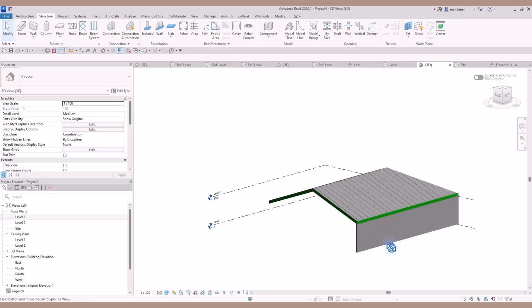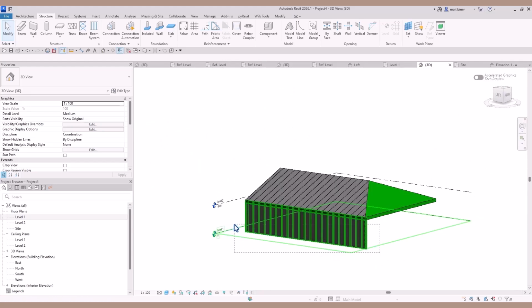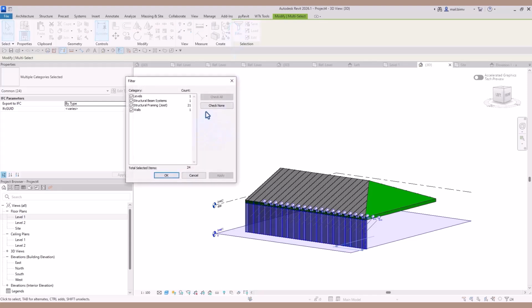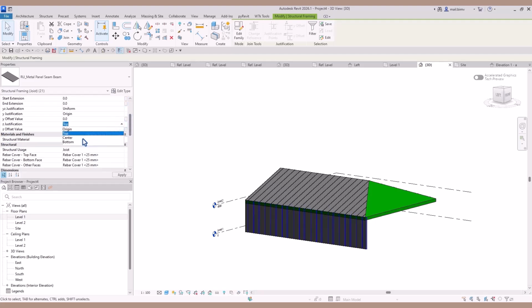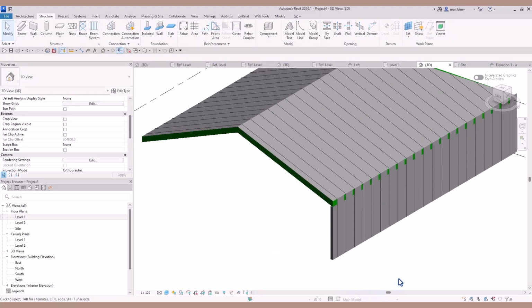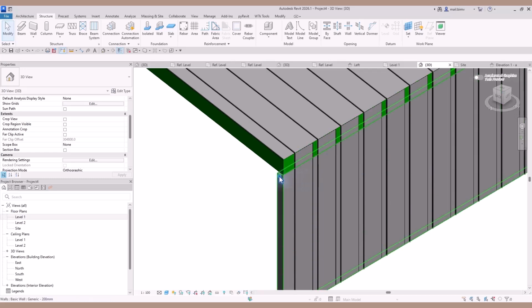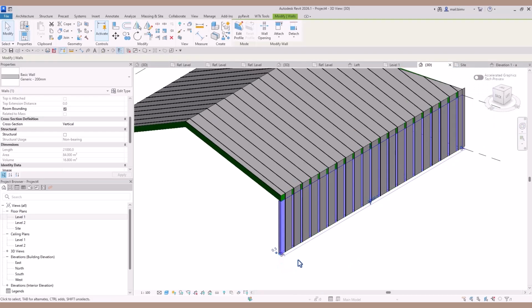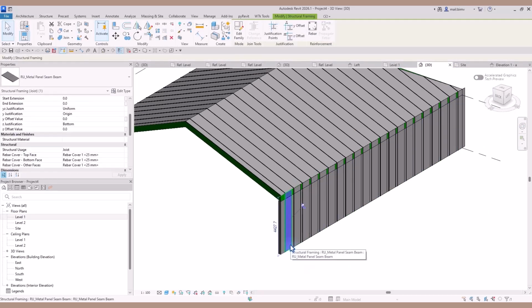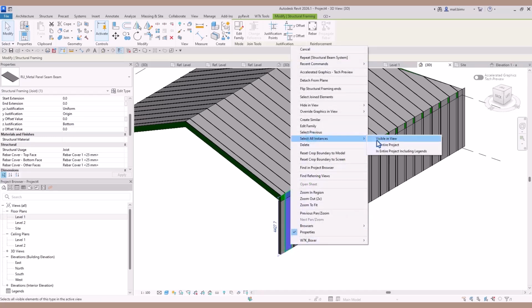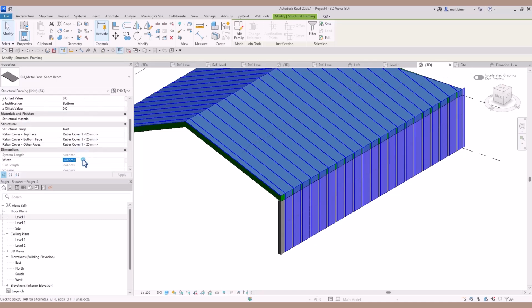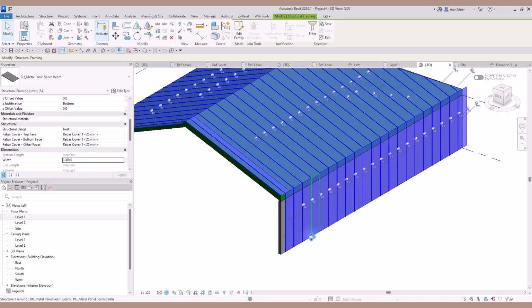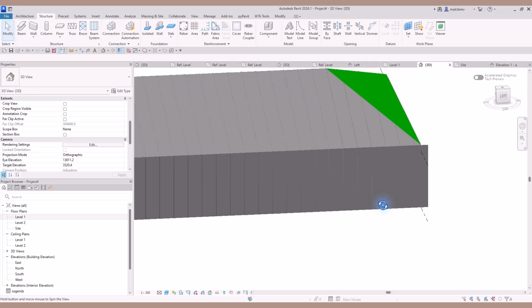I'm trying to select the beams in order to modify the justification, so I will use a frame and filter that, and switch from top to bottom. And make sure all those beams have the width of 1000. Perfect.